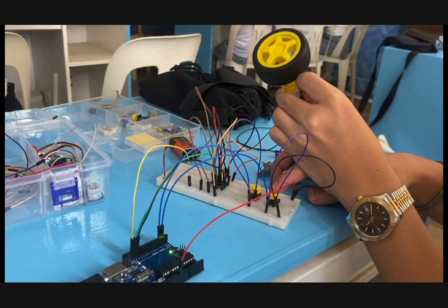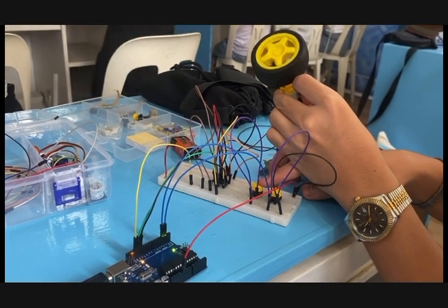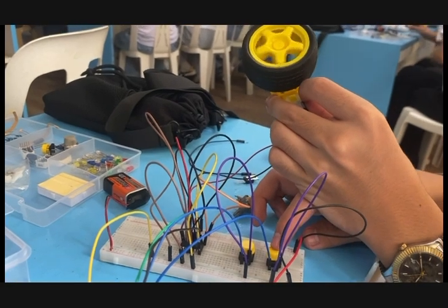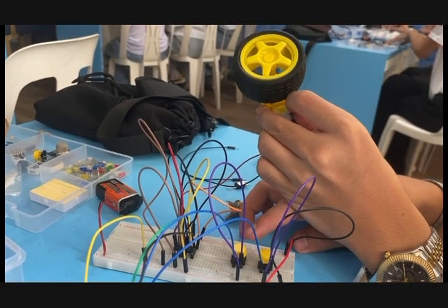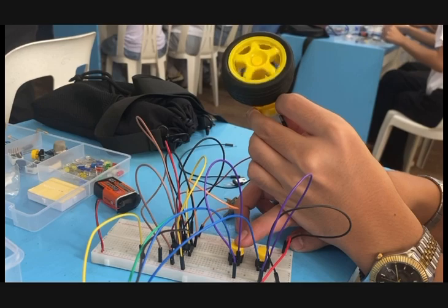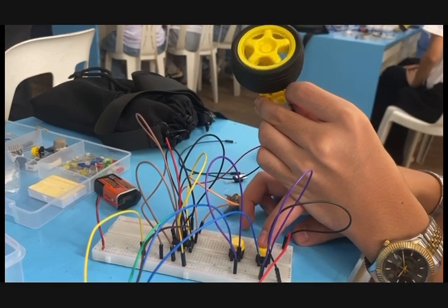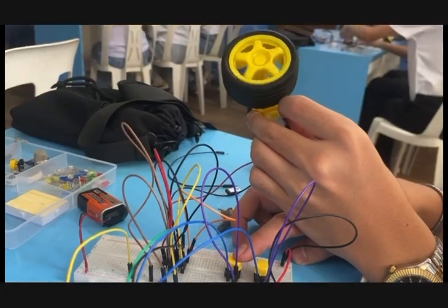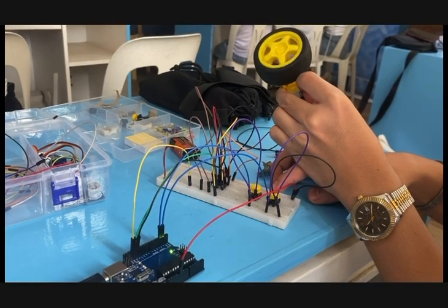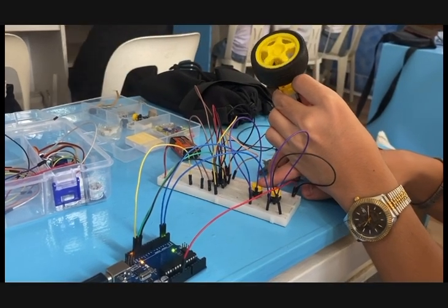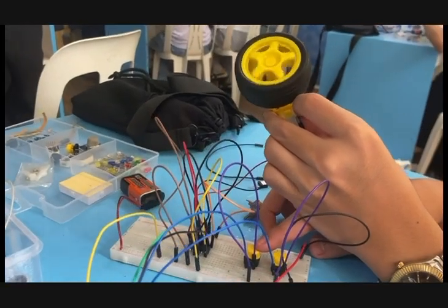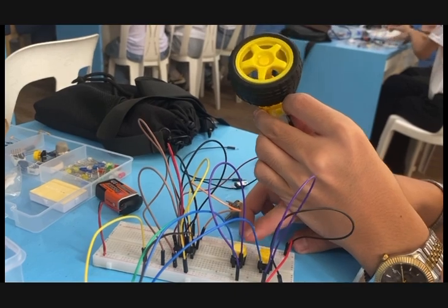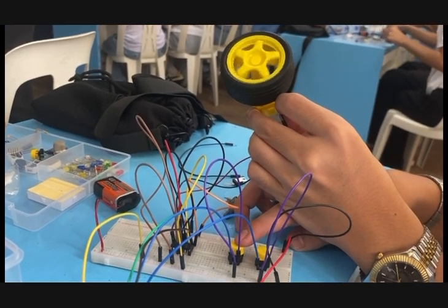We used two push buttons with the L293D motor driver to control the motor's direction. Pressing one button made it spin forward, and the other made it spin in reverse. If no button was pressed, it stopped. We encountered button bounce and wiring errors, which we solved by securing connections and using pull-up inputs. This system can be applied in robotic arms, motorized vehicles, and manual control panels.